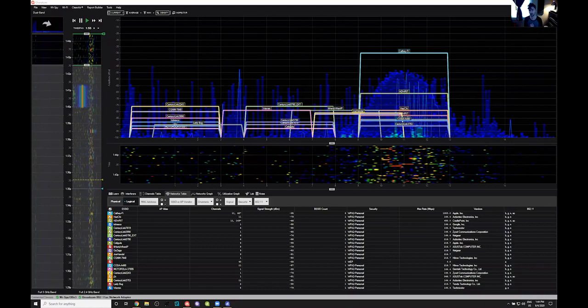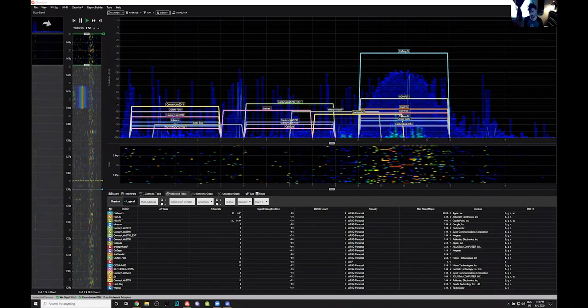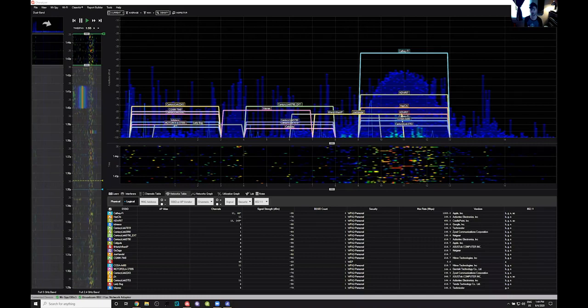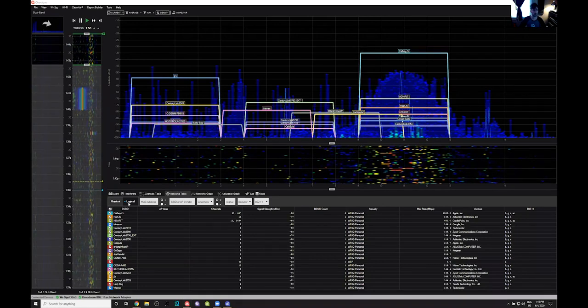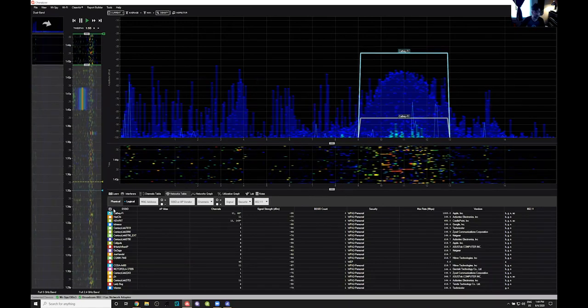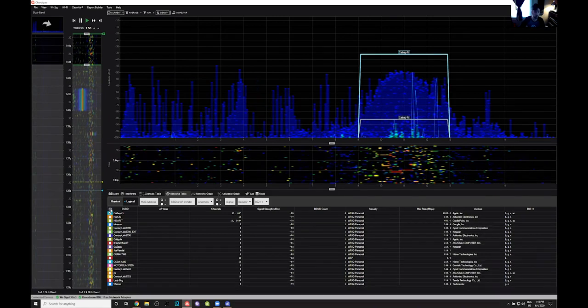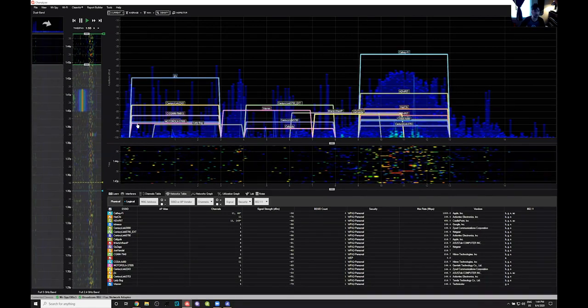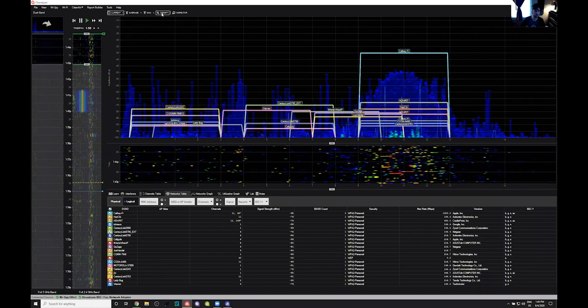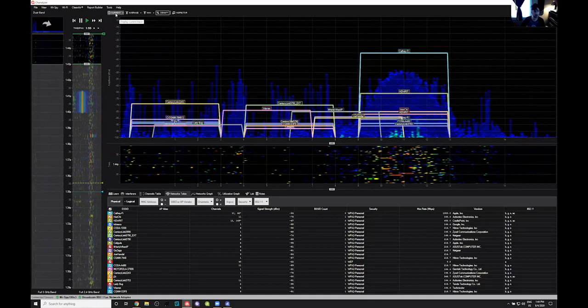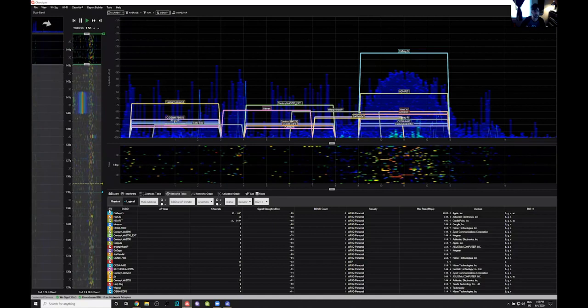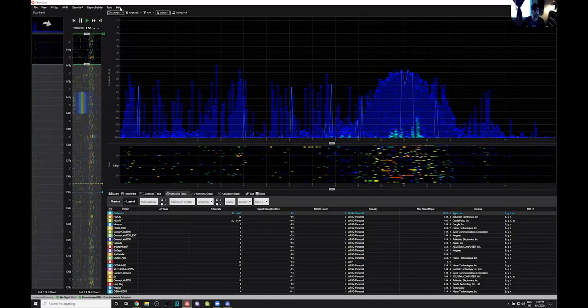Let's see, Naveen had a question. I don't see networks tab to bring up networks drawn on top of the graph. Okay, good question. One thing to keep in mind is, to see networks, not only do you need to have a check mark placed next to them over here in the networks table. And depending on the version of Chanalyzer you have, this one is a little bit more updated, there are some toggles up here in the top which show you the current trace, for instance, and I'm going to take off the networks so that you can actually see what I'm talking about.